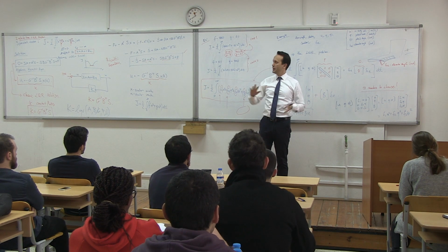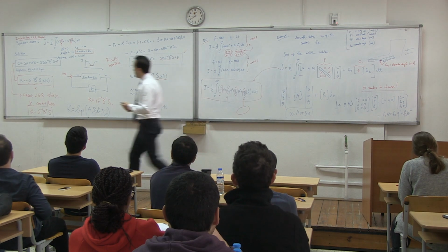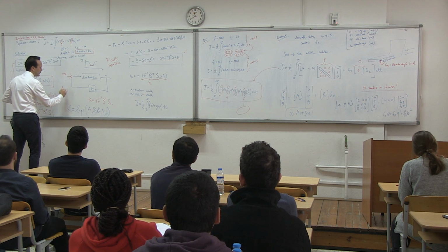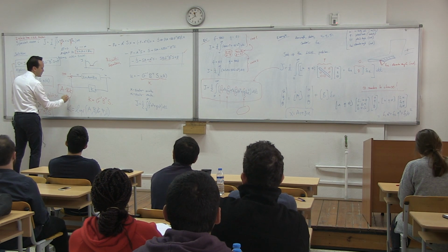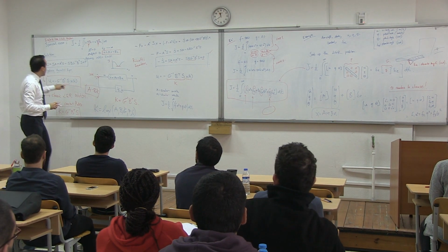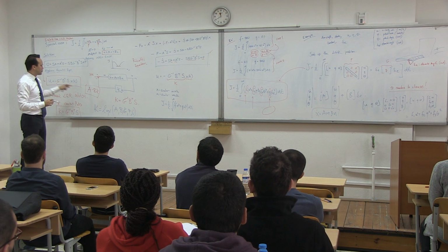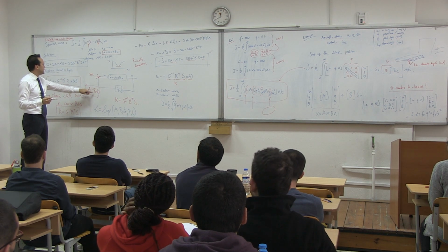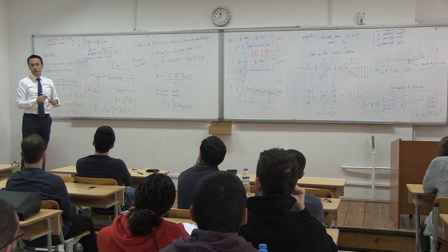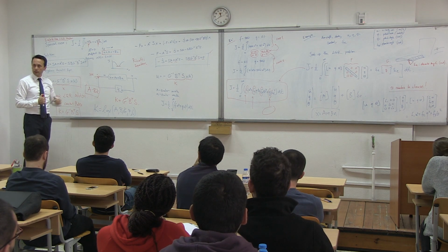Right? That's another question. I don't know where the eigenvalues will go. Where will the eigenvalues go? Well, this is K. The eigenvalues will still go to A minus BK. This is still the closed loop system matrix, except K is now this. So where are the closed loop eigenvalues? Well, you can check. A minus B times K will give you the closed loop eigenvalues. Okay? We don't know where the eigenvalues move. That's not my concern in this problem.